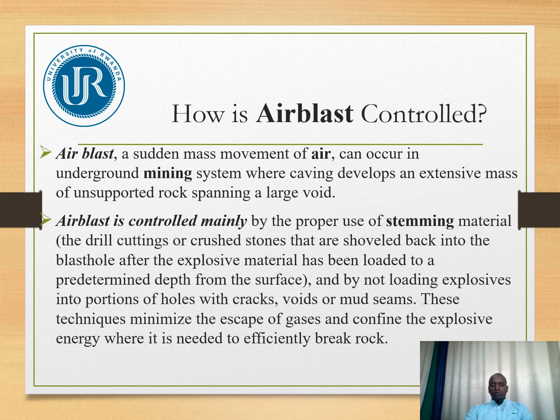Those are the drill cuttings or crushed stone that are shoveled back in the holes after the explosive material has been loaded to a predetermined depth from the surface, and by not loading explosive into the portion of holes with cracks, voids, and mud. These techniques minimize the escape of gas and confine the explosive gas energy where it is needed to efficiently break down